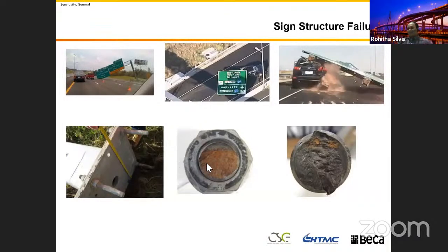They found that in most of the sign structures built, during service, the bolts cracked, and you can see the crack here. The sign structure designed with 4 small bolts, and the bolt cracks and it becomes unstable, and then it collapses. So this is quite risky. There's a massive risk you are posing to the traffic. So you have to design your sign structures properly.